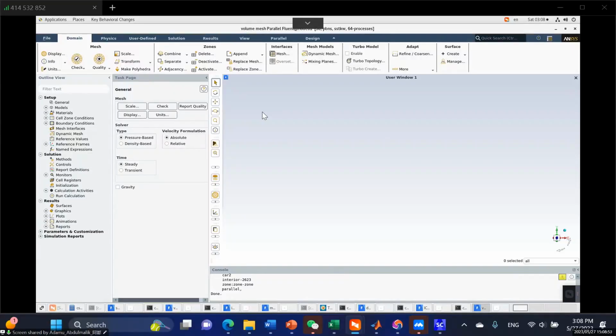Then after you use the option and your result is good, you can now say, okay, the computational parameters that I use are okay, my mesh is okay, my result is good, then I can make modification. Then if I make a geometric modification, I can say, okay, I want to use the same computational parameters to simulate.